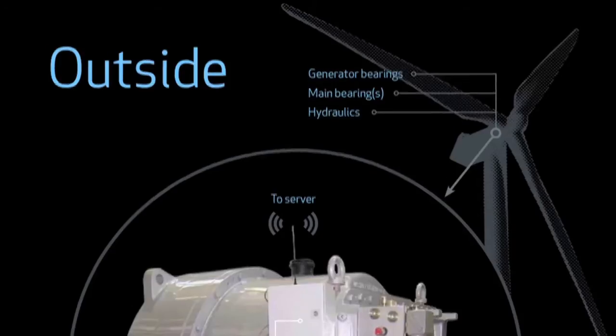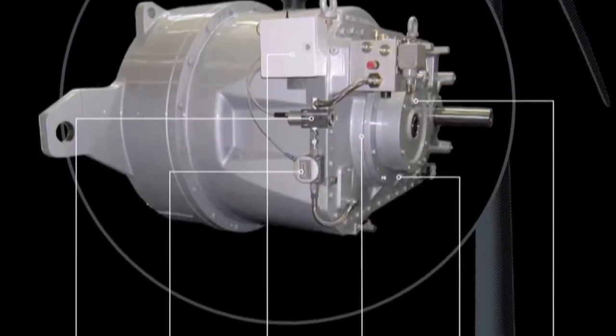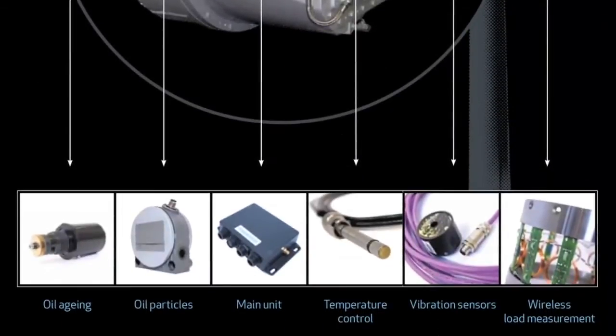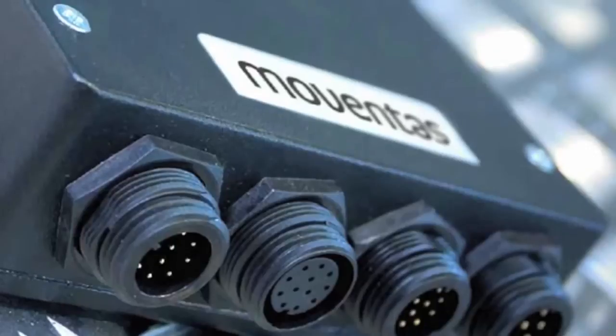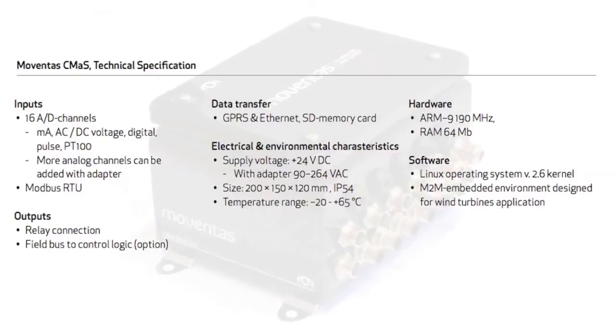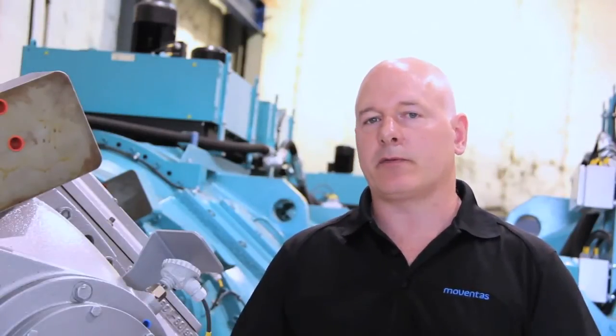Monitoring wind turbine gearboxes is complicated because of varying speeds and varying loads that are occurring constantly throughout the process. The system that we've developed uses an RPM sensor so that we can track the changes in speed and relate them to the FFT data that our vibration sensors are collecting. We need this correlation in order to be able to accurately extract the defect frequencies.